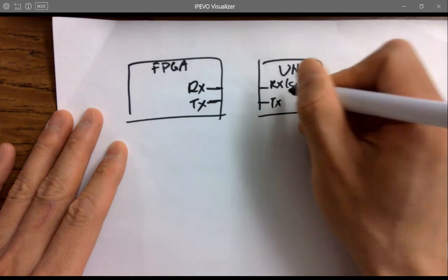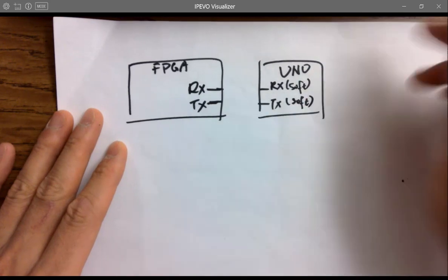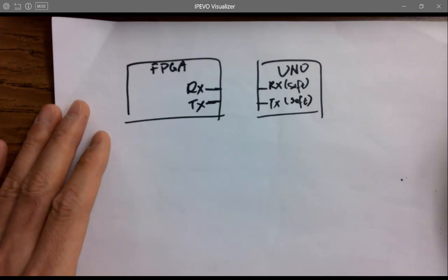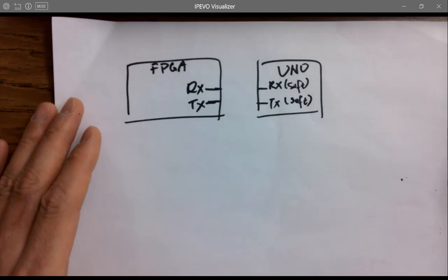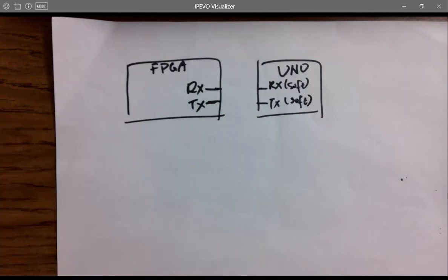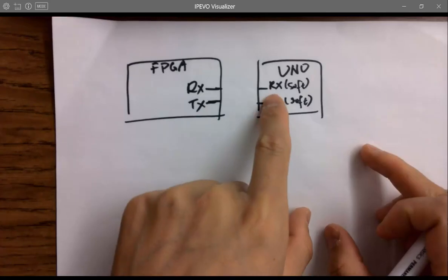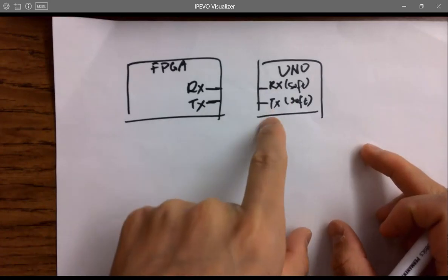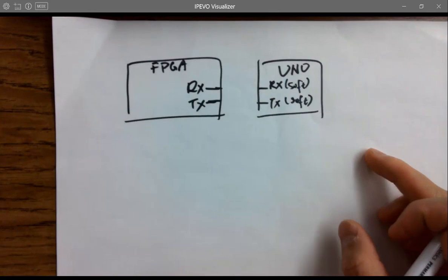So it's not a hardware RX and TX. It's something written in C++. You mimic the logic, looking at the timing diagram and do a time delay and then pull it down and then pull it up. It's just the ones and zeros. You can definitely implement it in software. Hardware is something like you have a clock in and the digital circuit will do all the sequence for you according to the state diagram. But for the soft UART, it's all written in C or C++ for the microcontroller.